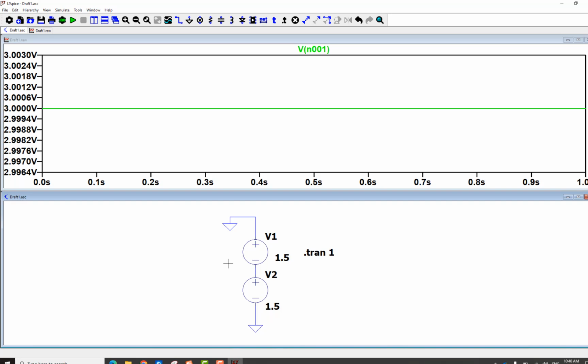In between, because the circuit itself is not right, it's gonna drain the current. It's gonna drain the battery very quickly, so it's not a valid circuit. It's changing over time actually. If you are draining a battery, the voltage of the battery will change, right? It's rated as 1.5 volts, but you are draining that really quickly, you are getting probably anything below like 1 volt very quickly. So it's changing.